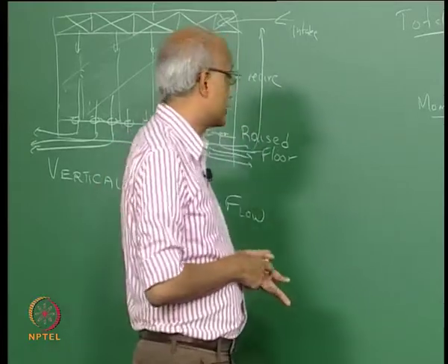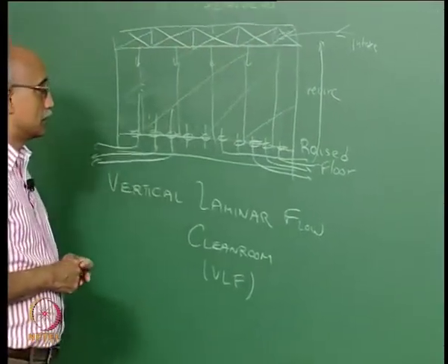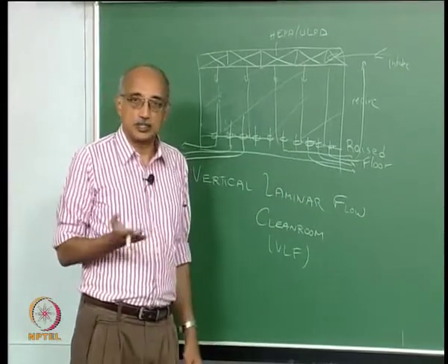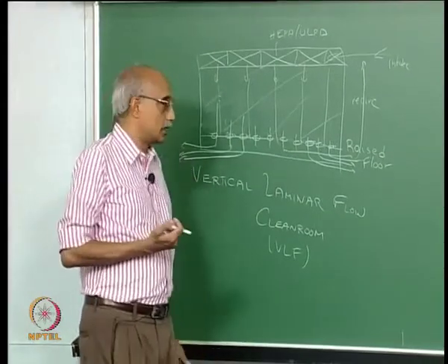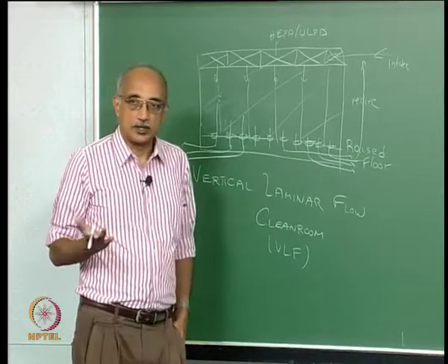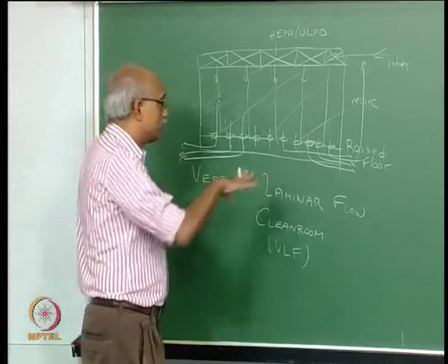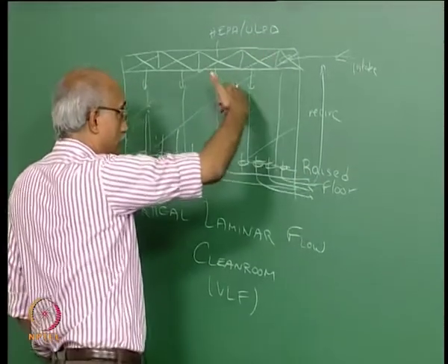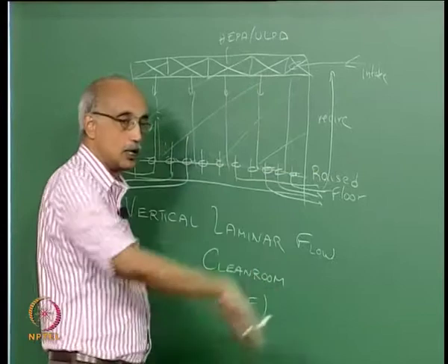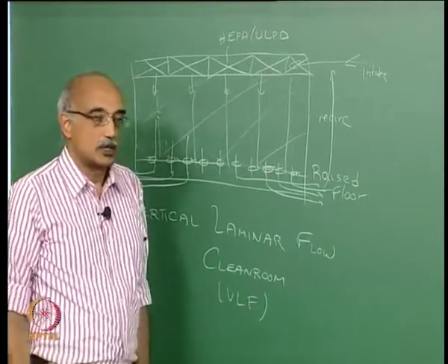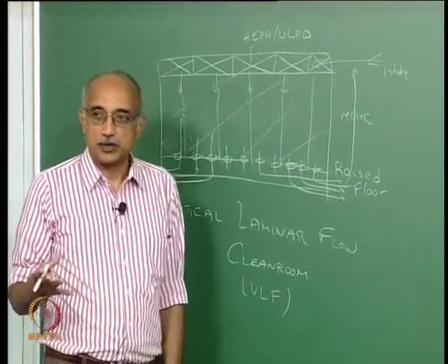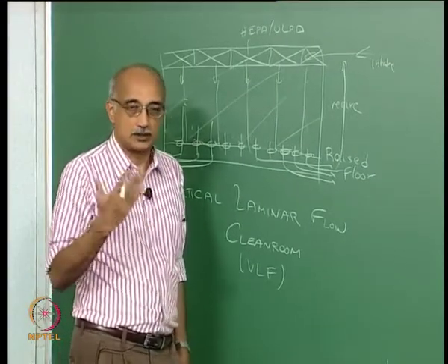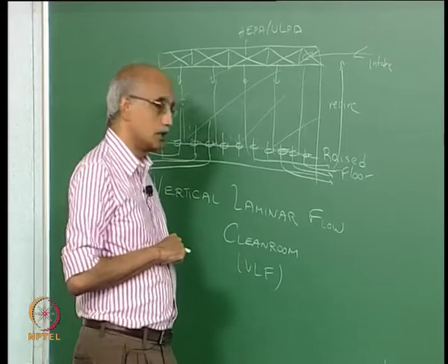The boundary conditions you will have to impose for the various situations. For example, along the walls you can say no slip boundary condition, which is a Dirichlet type of boundary condition, but near the flow paths, the intake path as well as the outflow path, you may want to impose a Neumann type of boundary condition which says that the gradient is 0, del v by del x or del v by del y equal to 0.